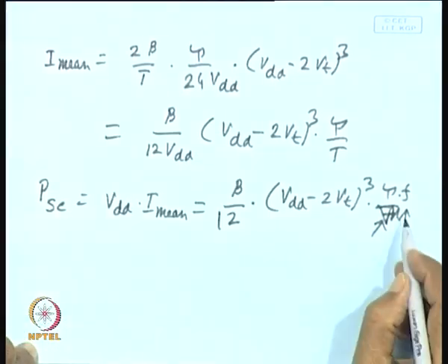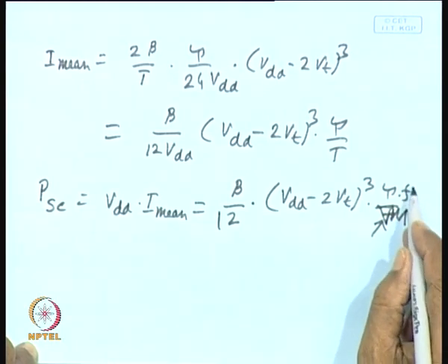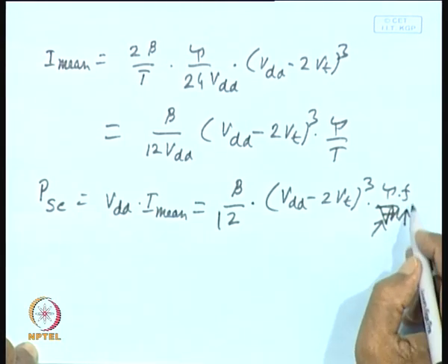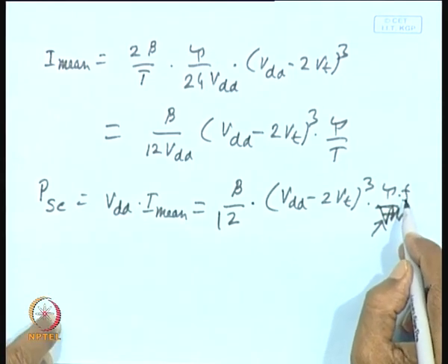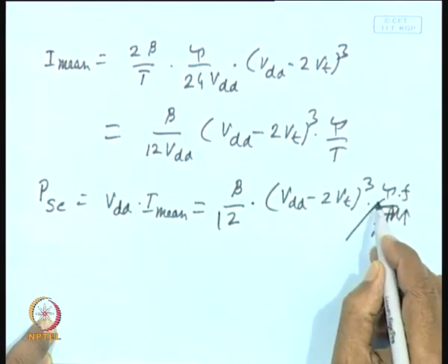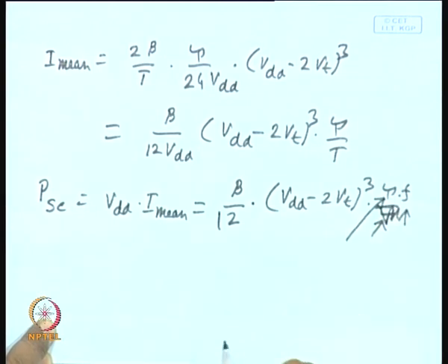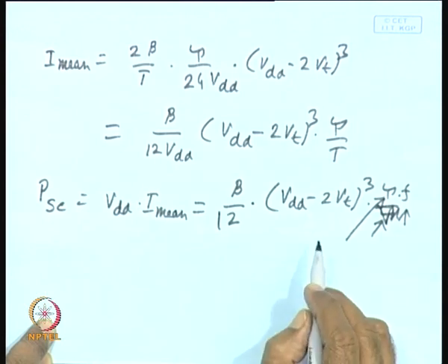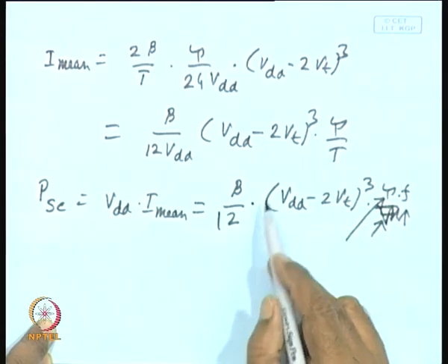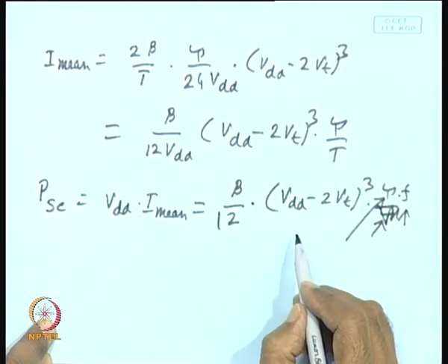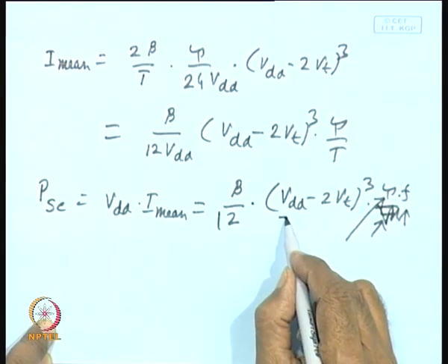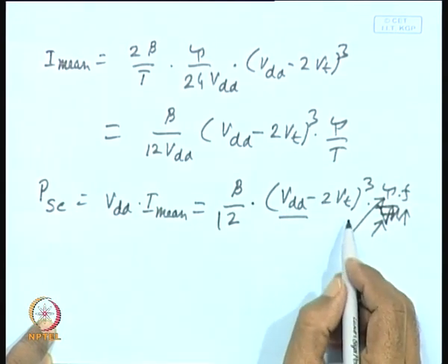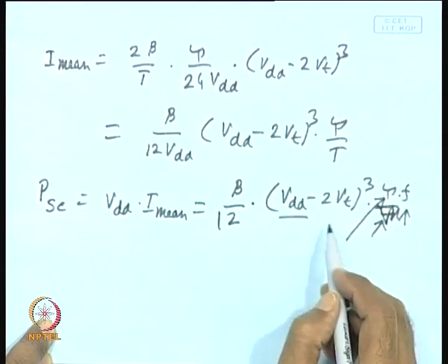which you can control. One is the frequency of operation, but we usually cannot compromise on performance. That is the reason why we cannot really reduce frequency to reduce short circuit power dissipation. However, we can reduce tau. We can also adjust the load capacitance, which can be increased to reduce the short circuit power dissipation. And of course, supply voltage scaling, or reduction of the supply voltage, is the most important parameter that can be used to reduce the short circuit power dissipation.